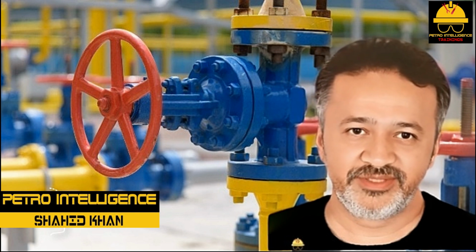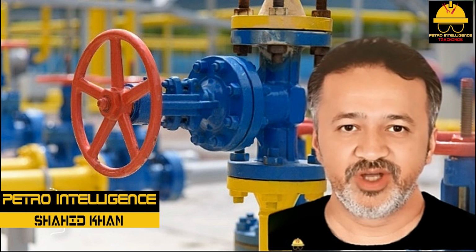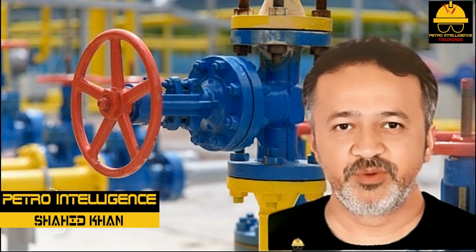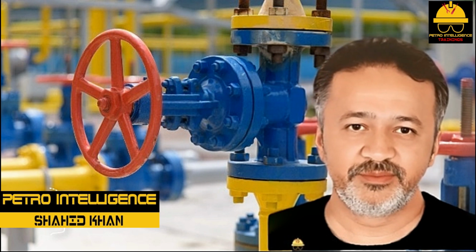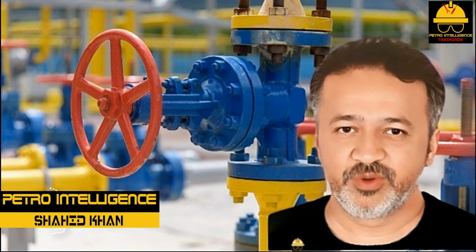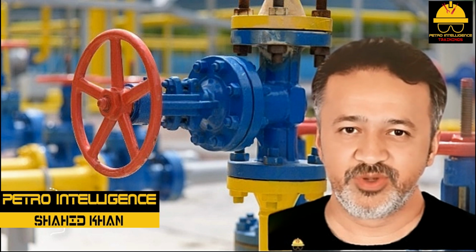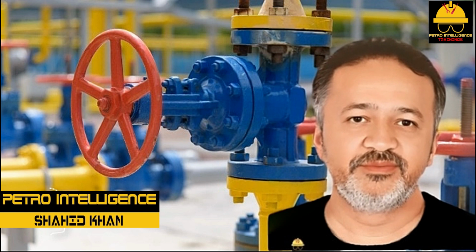Cold service relief valves ice up around both the inlet and discharge ports of the valve. Warm service valves are hot on both sides of the valve. Most relief valves discharge to the cold or warm flare drum and ultimately to the flare. Some relief valves, such as those in steam service, discharge to the atmosphere.